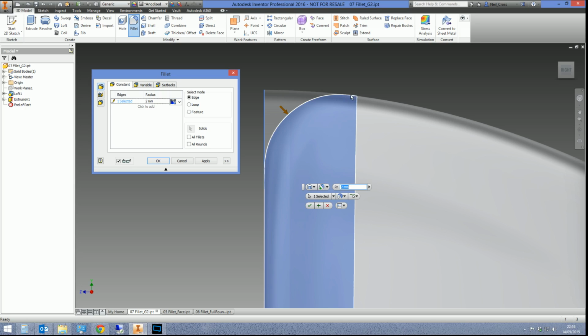It's sort of coming out in a very smooth fashion, and then it blends off and joins into the next edge. It's known as a G2 fillet, but if you go from tangent to G2, you can actually see the difference. It is quite dramatic when you look side on, but if you zoomed out, you can't really tell. In terms of manufacturing, do you need to do this?